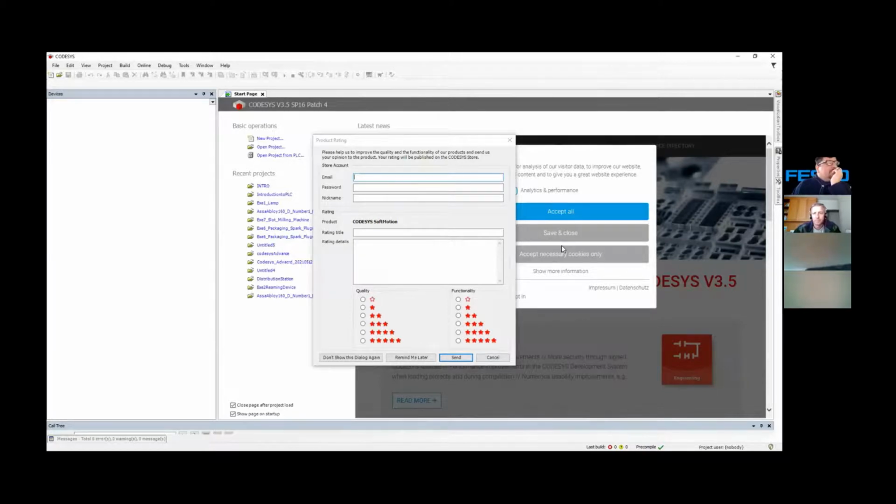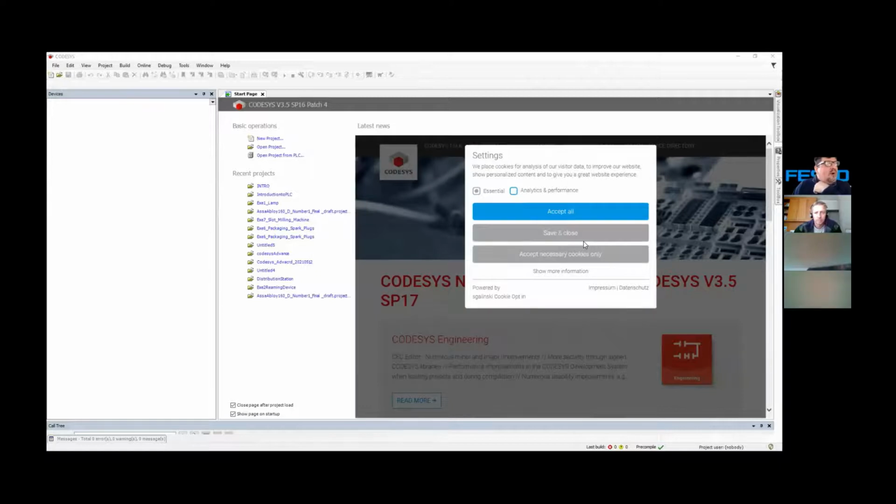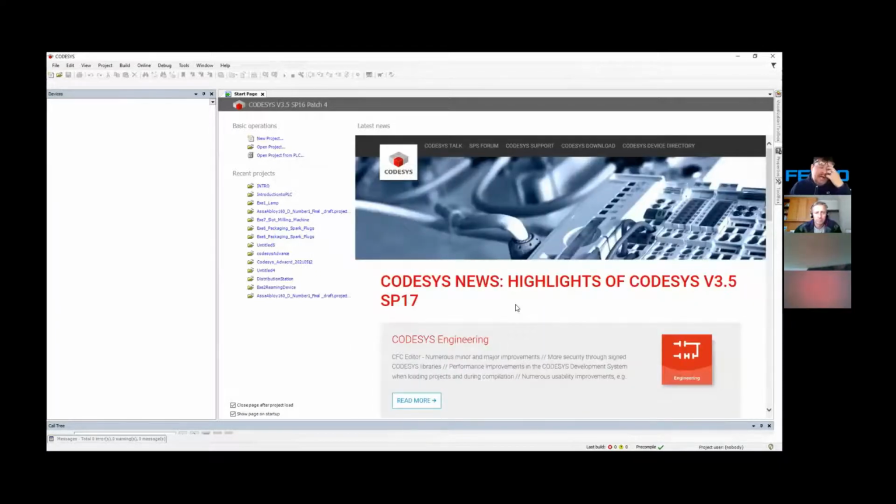Okay. Right, guys, now listen to me. Now I want to put everything that I've discussed with you into a more practical understanding of the PLC itself. Here we've got CODESYS open. Now to start CODESYS, normally, you install it onto a PC. It's a Windows-based program. And then you double-click your icon to activate the software. Within the software, you go to your menu bar on top to File.